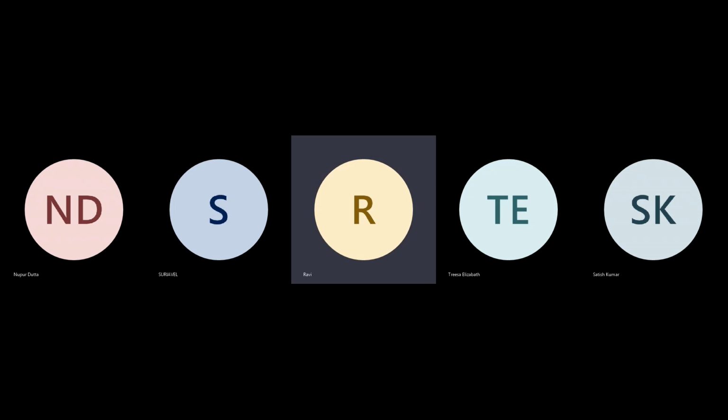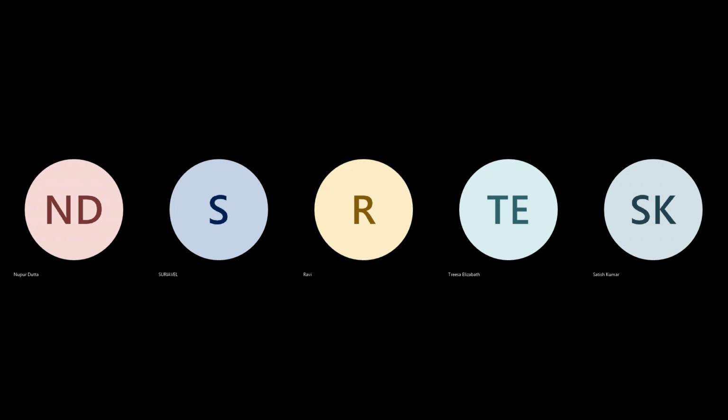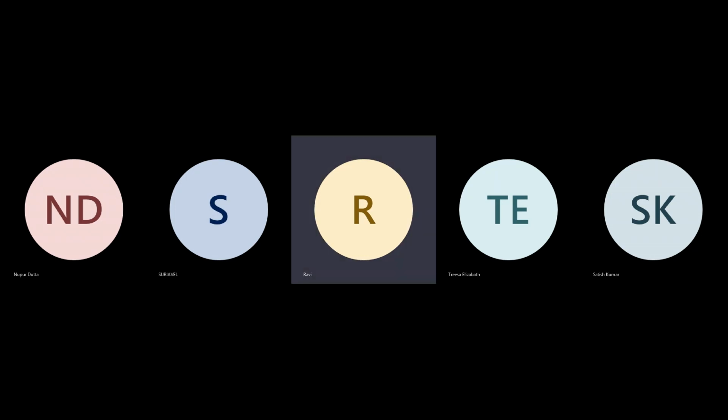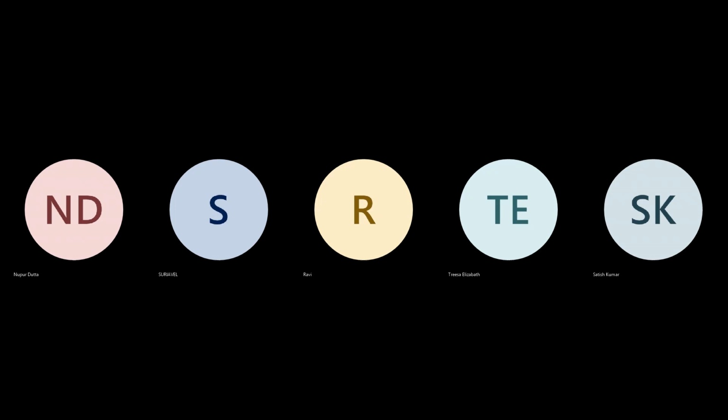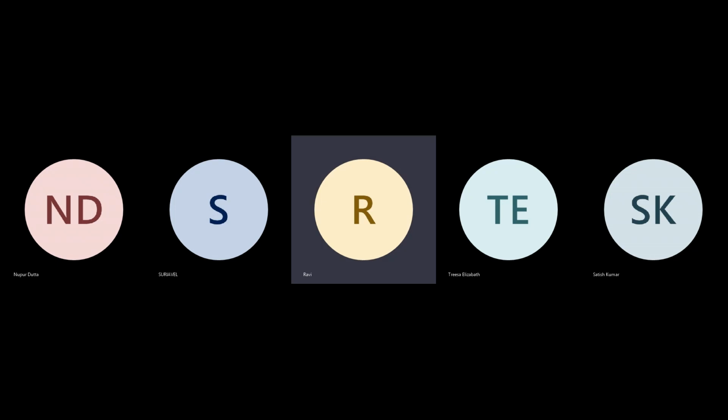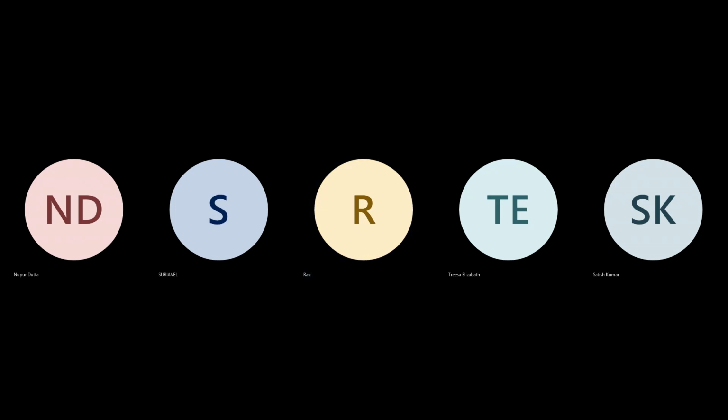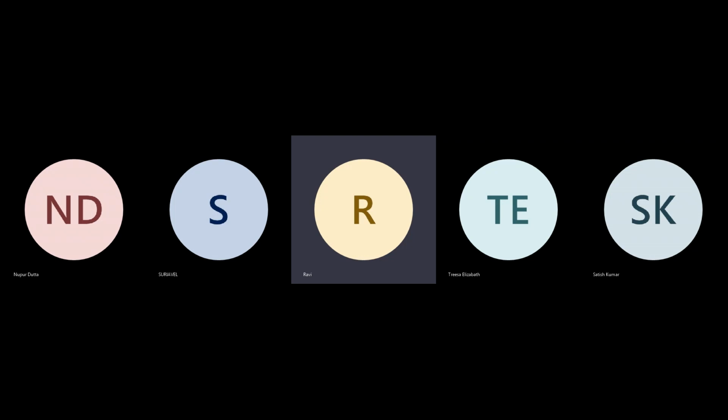Then you will see that after this, these cells are getting placed somewhere far away. After coarse placement, you notice, hey, this is critical for my IO, this is actually causing me trouble. That is when you give the initial feedback: I need macro placement, I need some net weights for this. That's why you start working and give the tool more guidance. You have to make the tool work for your requirements, not you work for the tool.